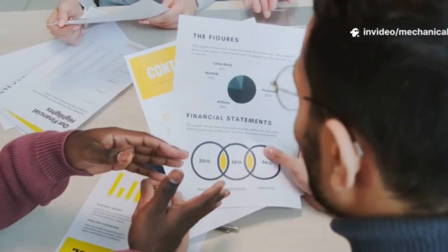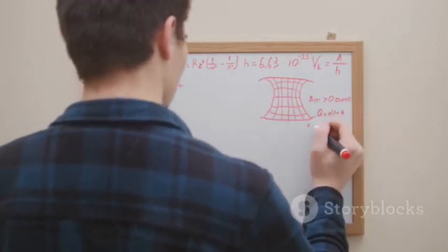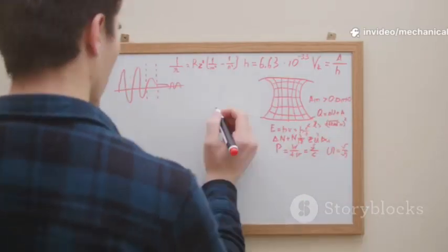Step 4. Check your work. Are arrows correct? Labels clear? Add an XY axis if needed. A quick review prevents mistakes. That's it. You've made a professional FBD. This skill unlocks the power to analyze any physical situation.